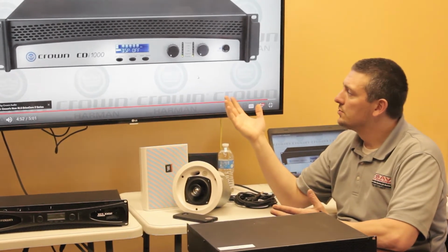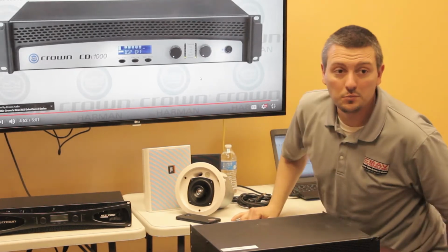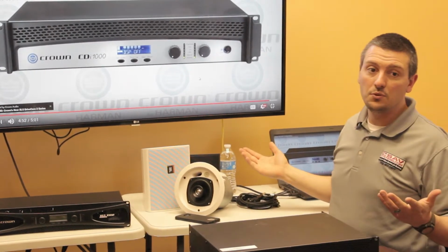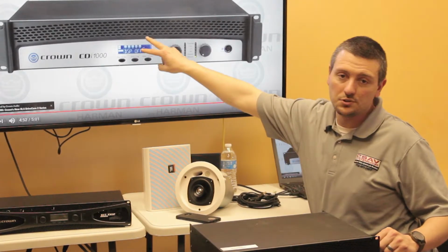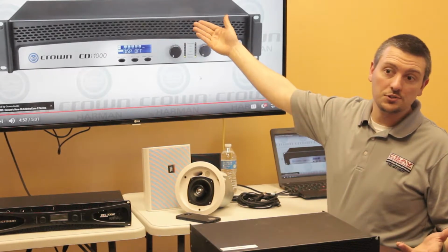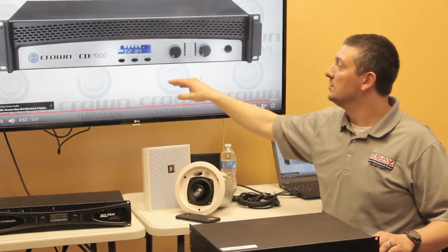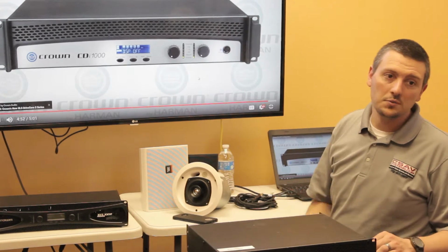I've gone on service calls before, which luckily, nothing got screwed up or blown out, where we've got 70 volt systems and something happened where somebody was touching something and switched over channels 1 and 2 from high Z, which they should have been, to low Z. So being able to lock out the front panel, basically everything on here can just be inactive and they just have the volume controls.